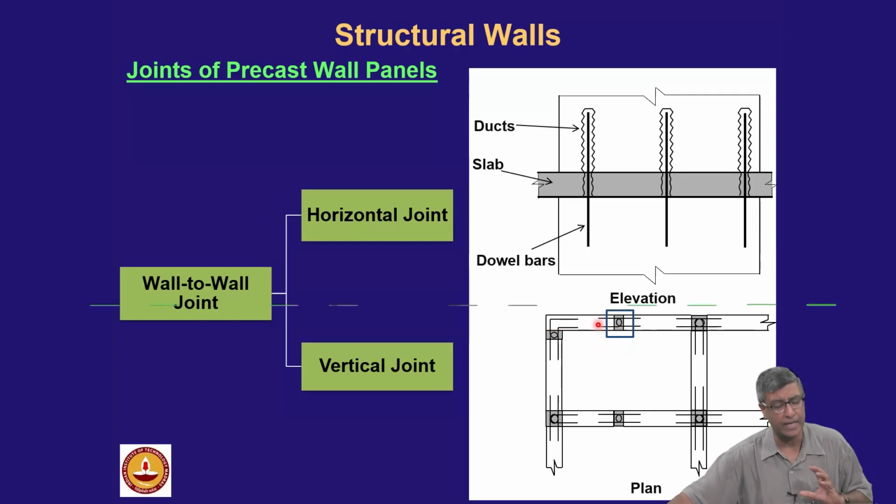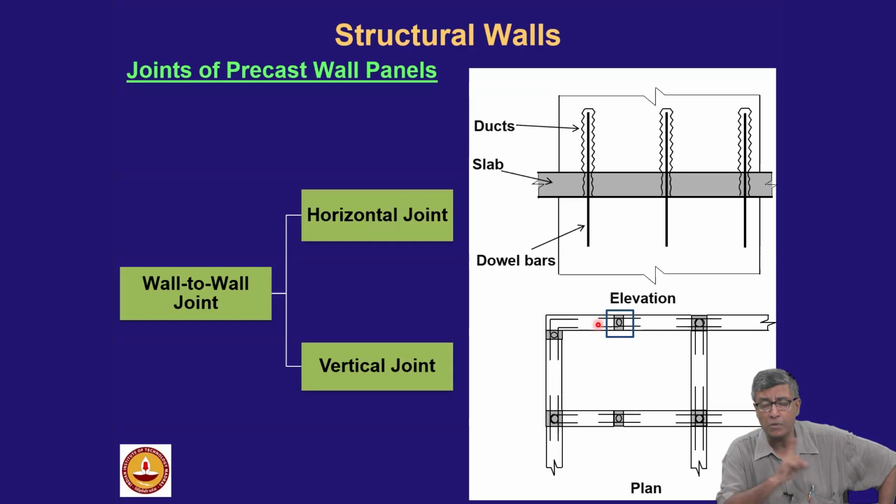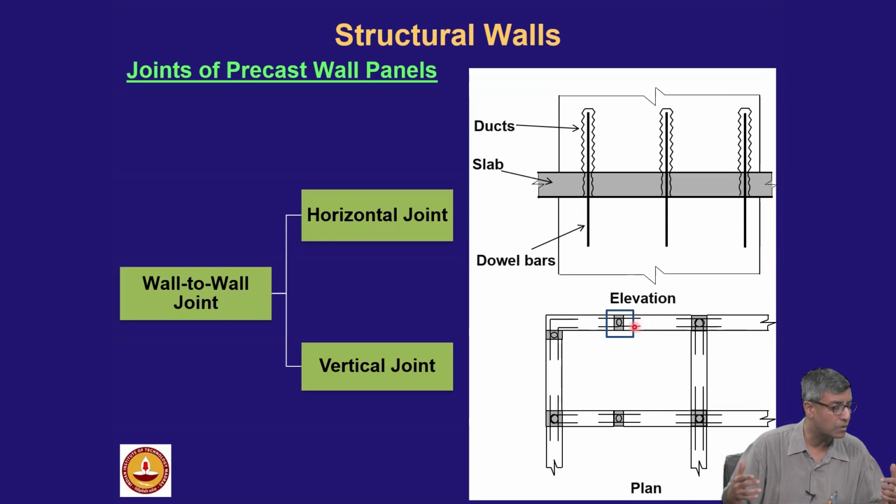But this is one way of classification: horizontal joint versus vertical joint, and both these are considered to be emulative. But let me tell you, emulative does not mean it will behave like monolithic. That's a misnomer. At least this type of joint is weaker than had there been no joint, because the reinforcement is not continuous.